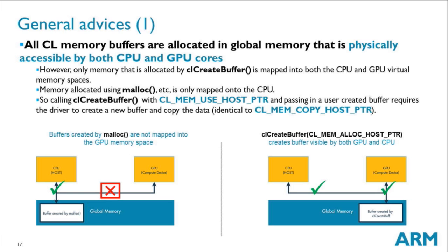This slide explains the main difference between a general desktop GPU and a mobile ARM GPU. Generally speaking, in a heterogeneous system composed, for instance, of a CPU and GPU, we have two different memories, one for the CPU and one for the GPU. What does it mean? It means that if we want a computation on the GPU, we need to move the data before starting the computation. But having two different memories introduces latency, and it increases the power consumption because the memory transfer is not free. In an embedded system, it is really important to reduce power consumption as much as possible.